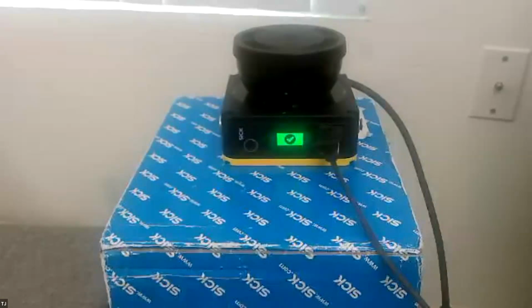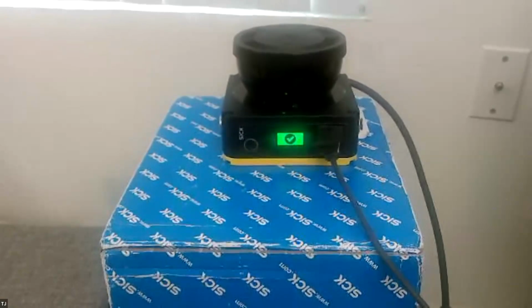All right, TJ, can we change configurations over the network, or do we always have to connect to the safety scanner directly? So you can change it over the network. We do have those system plugs which have the Ethernet protocol, Ethernet plugs. But the thing is, the device cannot be in an on state. The device will turn off and then restart again, and while you're changing it, it's not going to monitor anything. So it can be done, but you'll have downtime during that time.